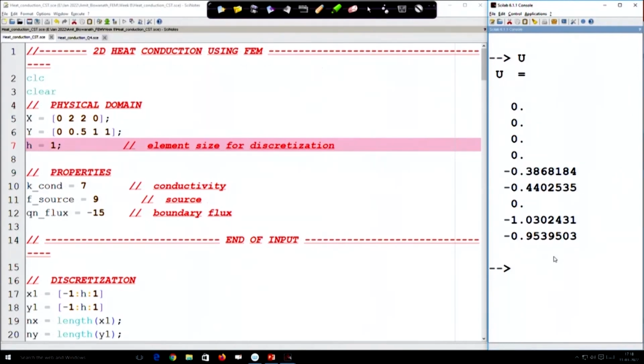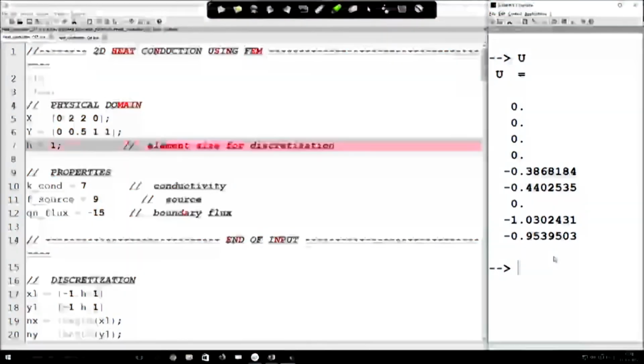If you recall, when we talked about errors in the finite element method and how they are represented, there are different measures of error. One is the absolute maximum value, meaning the maximum deviation from the true solution. But the other two, whether it is the L2 norm or the energy norm, involve an integration, a summation, over the entire domain.